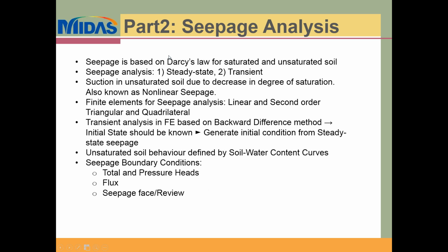Then moving on to part 2, which is the seepage analysis. It is based on Darcy's law for saturated and unsaturated soil. For the unsaturated soil, the Darcy law is modified, and the analysis can be performed both for the steady state and the transient state. Sometimes your soil might not be fully saturated, so in that case, the unsaturated behavior in the soil invokes the requirement of the nonlinear seepage. For nonlinear seepage, or also for linear seepage, you can use a variety of elements such as triangular or quadrilateral, and they could be linear or second order. At the nodes of these elements, the pore pressures will be calculated.